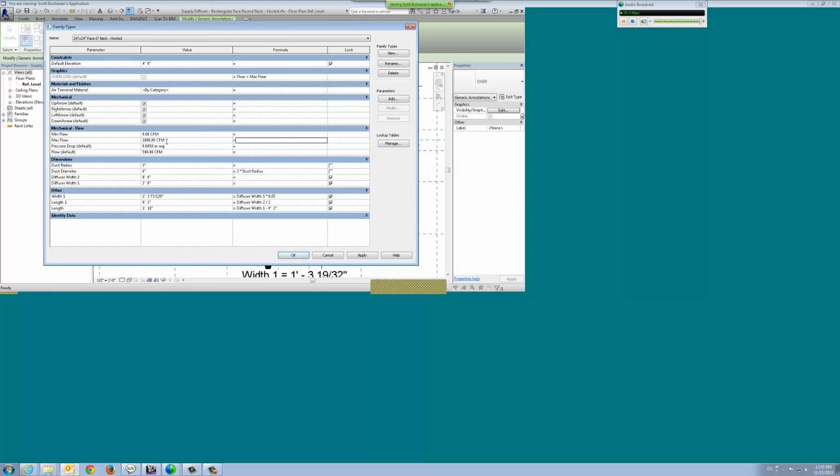And I could do something more elaborate, if greater than for the max, less than for the minimum. We can embed that in there. Keep it simple here. You can see it's going to do one instance of it as well. Now, we've got our full-blown formula support here as long as we're returning numerical values and so forth within Revit. But what I always recommend doing is keeping yourself a cheat sheet of formulas. Okay, if you've got formulas that you reuse all the time, go ahead and create an Excel file.